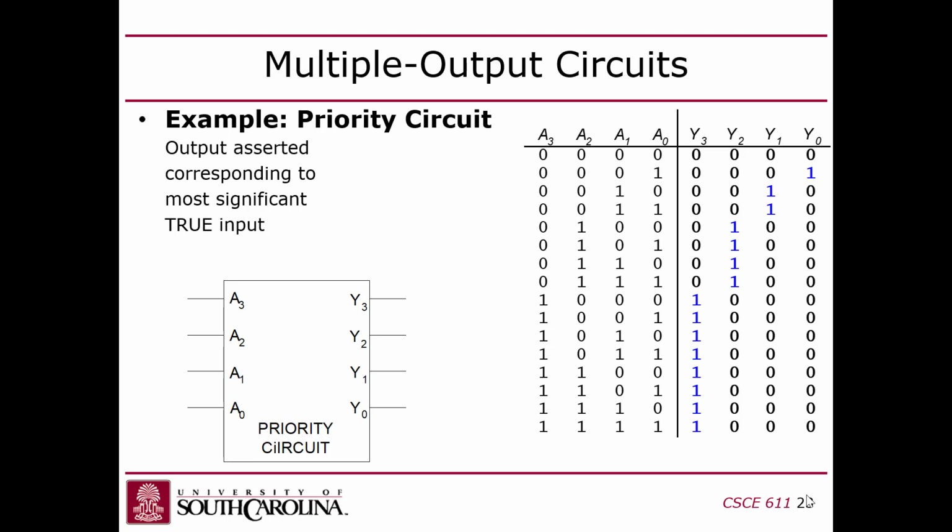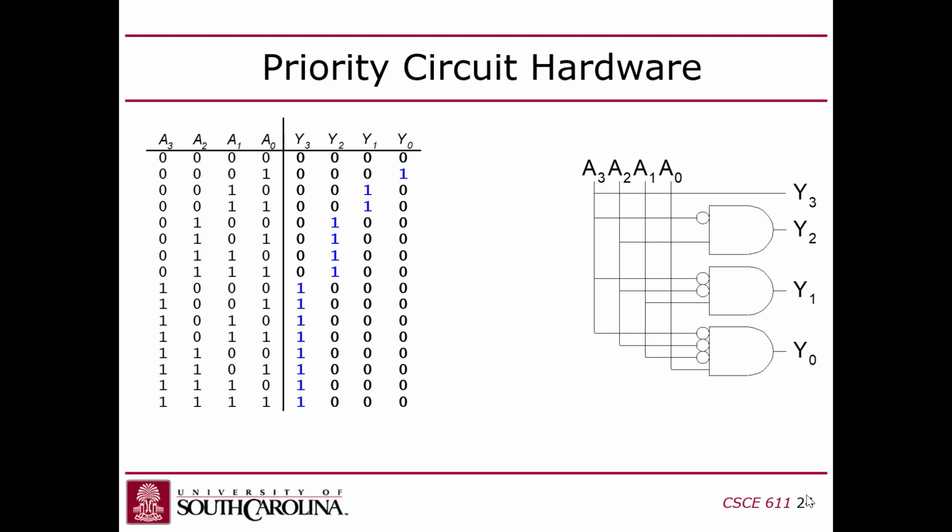Whenever you have a contention, you have a conflict, you resolve it through a fixed priority, meaning that, for example, if I have 2 inputs coming in, 1 and 0 both want to go to the output, then I arbitrate and allow bit position 1, the number 1, to go, right? So this is a priority circuit.